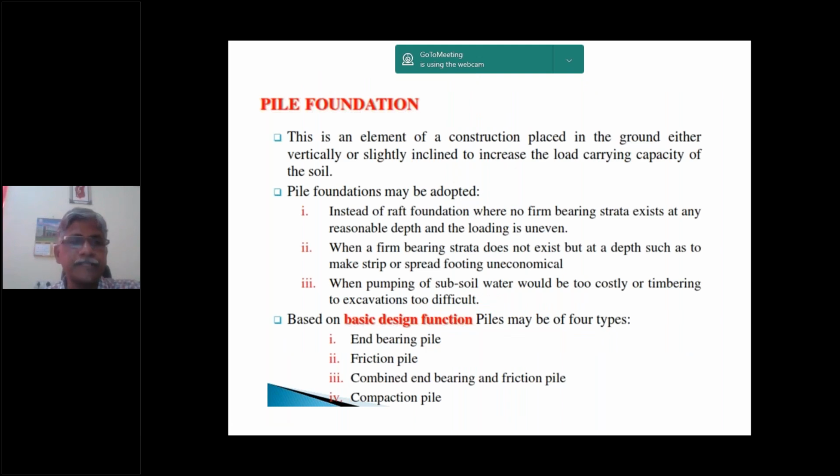All of us know very well that pile foundations are mostly preferred where huge, heavy loads are required to be transmitted to deeper depths, and where the soil strata is very soft and loose. Those soils would not have much bearing capacity, so in that case it is required to opt for pile foundations. Based on the load action and placement, these are end-bearing piles, friction piles, combined end-bearing and friction piles, and compaction piles.